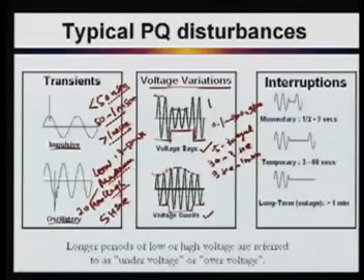So if your voltage dip is up to 1 minute, then it is called voltage sag. There is always a possibility that your power system operates, especially in our country, with a continuous voltage dip, meaning a voltage dip for a longer duration, even for hours, especially due to heavy loading. That is not a power quality problem, that is a different type of problem.